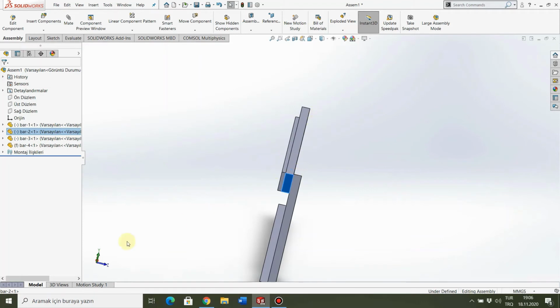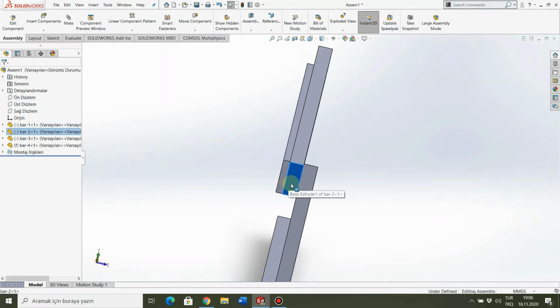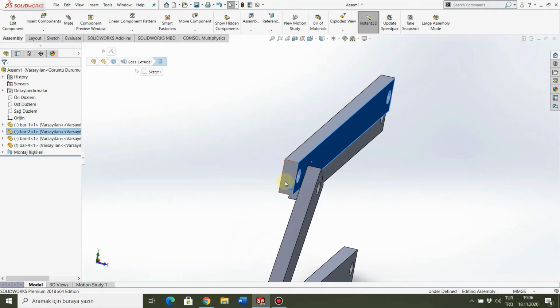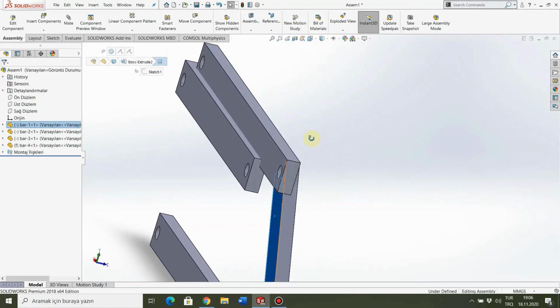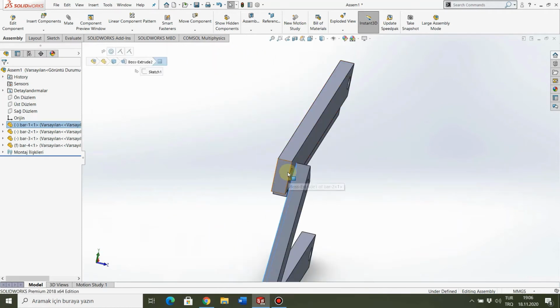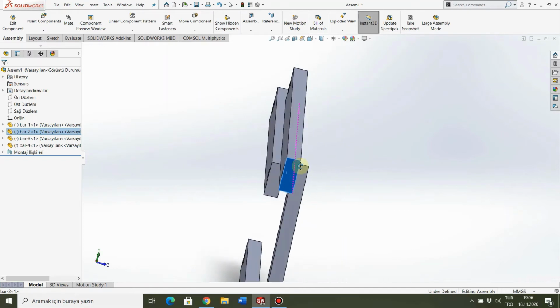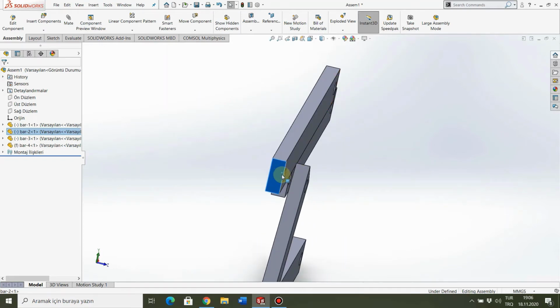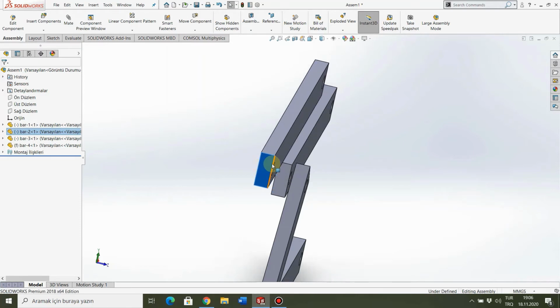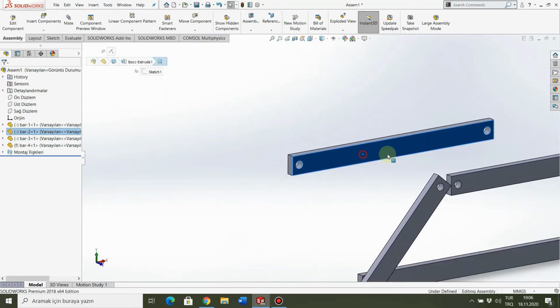This is the x direction. You can see here. This is the up and down is y direction, and this is the z direction. So when we coincident with these two planes, I only restrict the motion in z direction. I cannot move it in plus z or minus z, but I can move it in x and y directions.